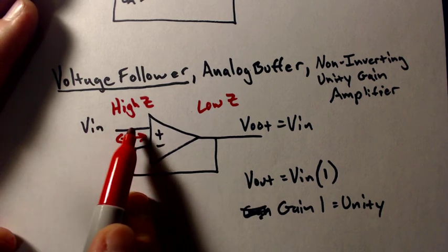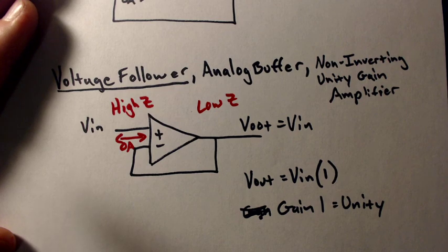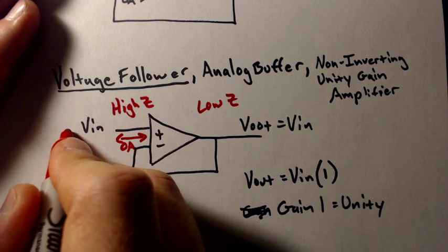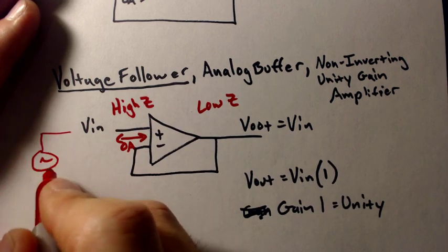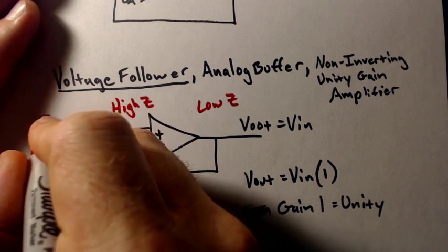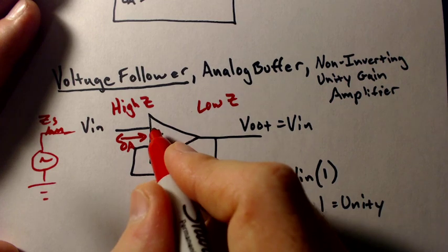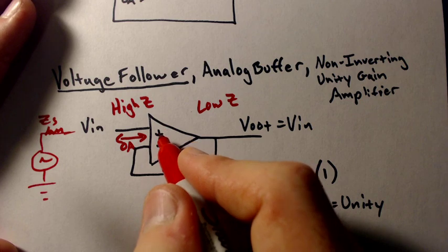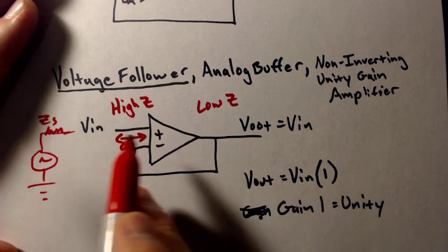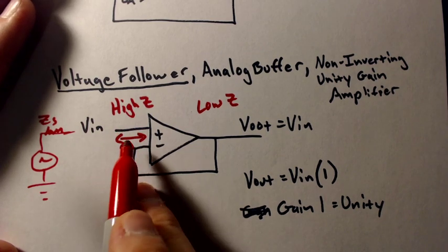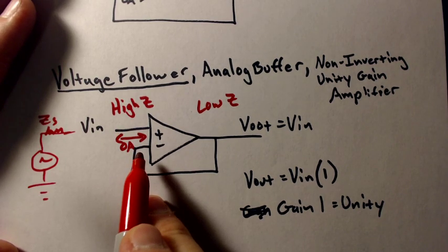Because if I connect something over here, remember I said in the real world, you're always going to have a difference in impedances between the source. You have a ZS, and you have another resistance in here that I'm not drawing, tied to ground, which is also an impedance. And then you'd have to do a voltage divider between these two to find out the true voltage at this pin. Well, once we use an op amp,